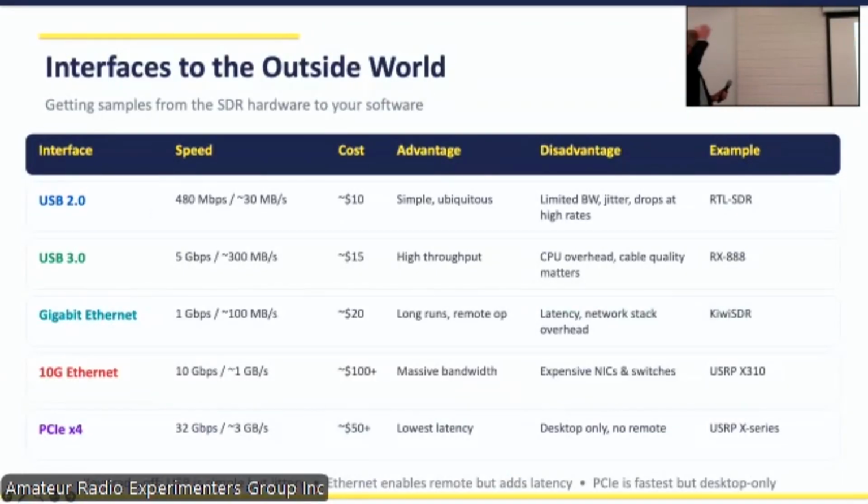Interfaces. This is scary. Anytime you look at USB, it doesn't matter how fast they say it goes, it's how well that USB times onboard your processor, especially if you're looking at some of these ARM processors that only have 2 cores. The timing is just abysmal. And what will happen is you'll tend to lose some of the packets because it's using a large percentage of the available bandwidth, and a timing or a buffer goes out.